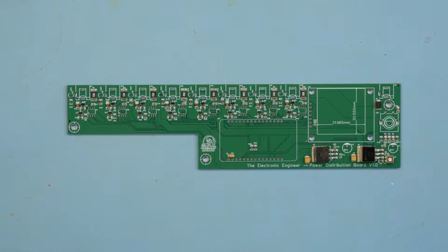Okay, so this is the power board, and as you can see, most surface mounted devices, the small components already have been installed. That was done by my manufacturer on my request, so I don't have to do it. All I need to do is add the energy monitors and all the through-hole components. On this board you see the trim potentiometer here, that is used to adjust the power output for some outputs.